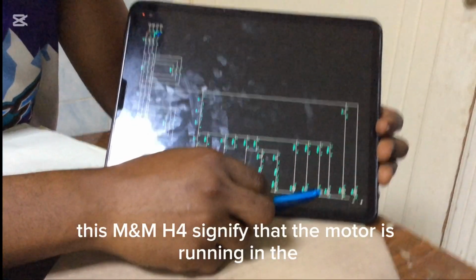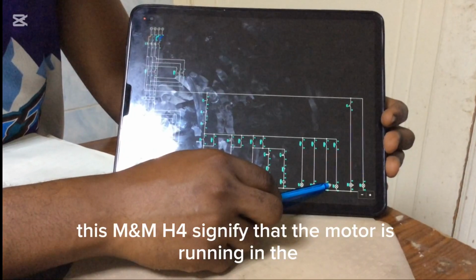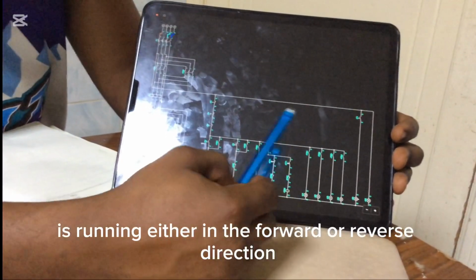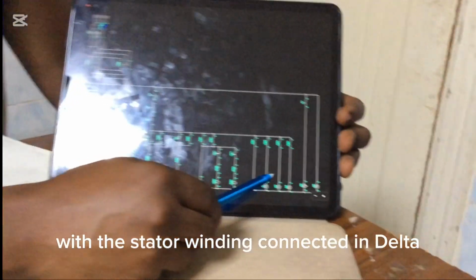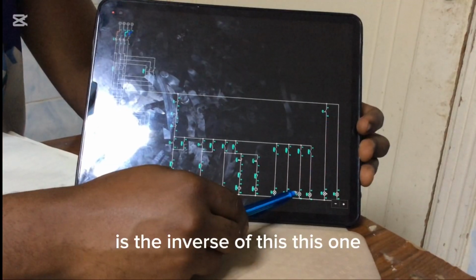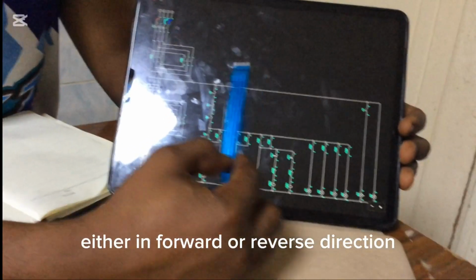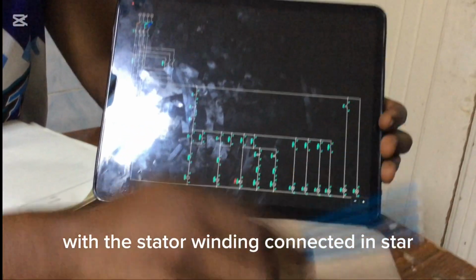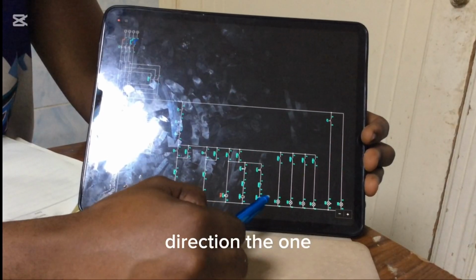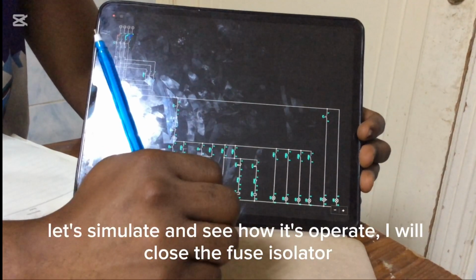This H4 signifies that the motor is running in either the forward or reverse direction with the stator winding connected in delta. Same here, the inverse of this: this one will indicate that the motor is running in either forward or reverse direction with the stator winding connected in star. This one will indicate that the motor is running in reverse direction. This one indicates that the motor is running in forward direction. Let's simulate and see how it operates.